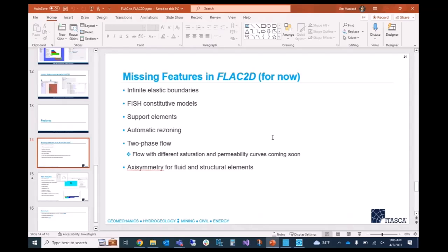You know, Van Genuchten and Brooks and Corey or something, or Zinn and Fredlund. I don't know, there's a whole pile of them, right? People who care about unsaturated soil mechanics like to have that control over the way that these things desaturate. That's mostly what people are using the two-phase flow logic for in the old FLAC.